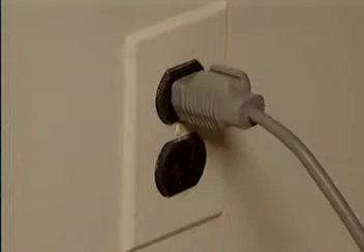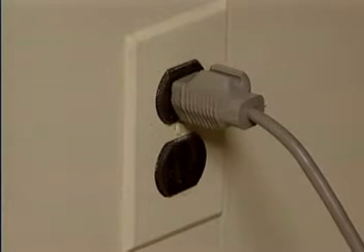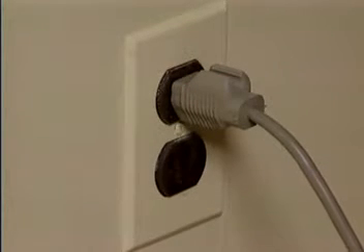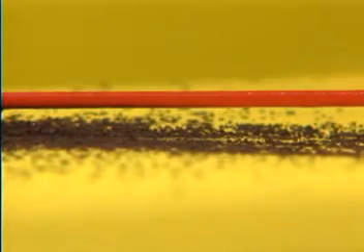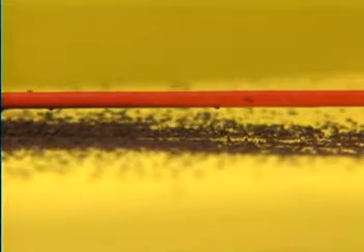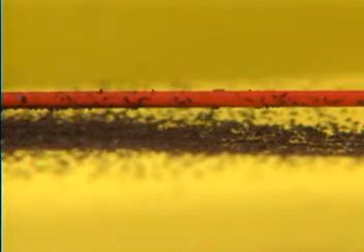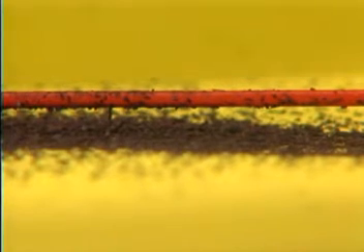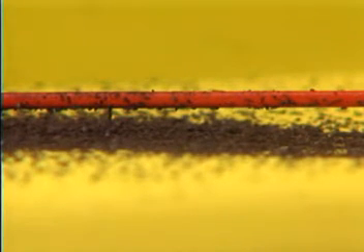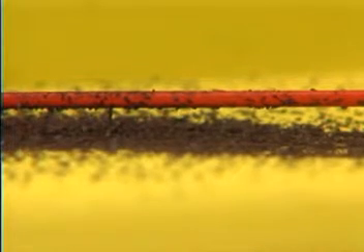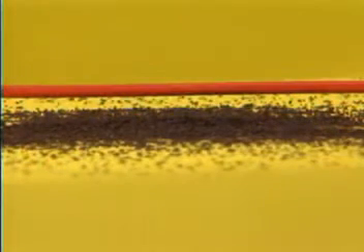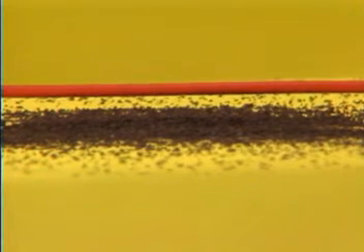Electricity produces magnetism. Any conductor that carries an electric current will act like a magnet. Let's use iron filings again. Watch what happens when a wire, which is connected to a DC source, is brought in proximity to the filings. Notice how they're attracted to the current-carrying wire as if it were a magnet. This is because when current flows in a wire, a magnetic field is produced around it. When the wire is disconnected from the DC source, the iron filings are released. The wire was temporarily magnetized by the electricity.